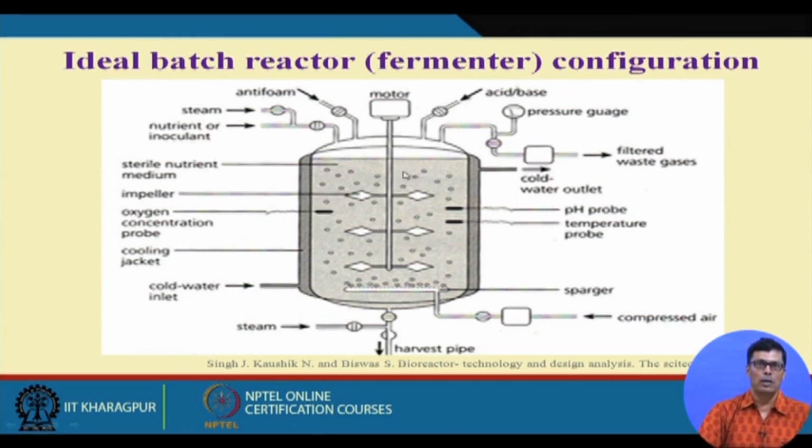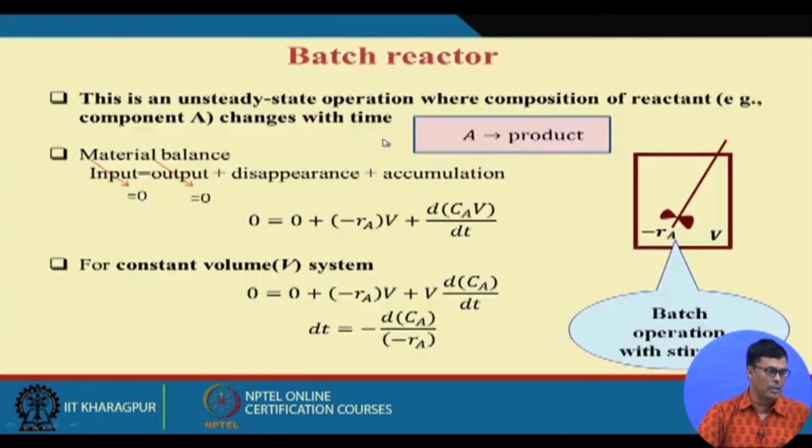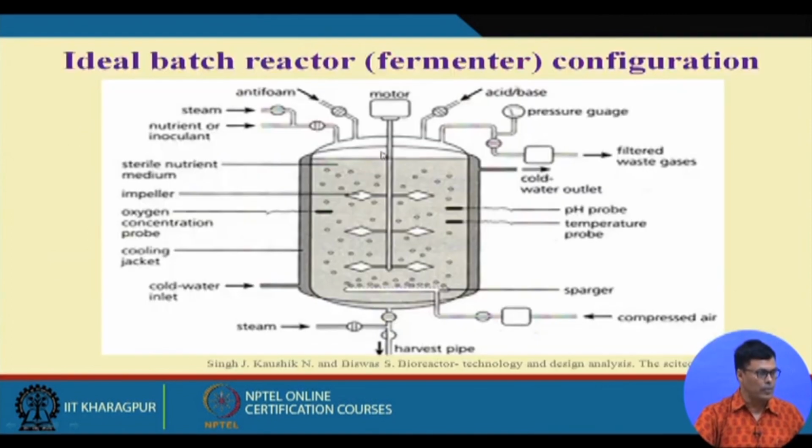So it should be perfectly airtight. To make it perfectly airtight, the air seal is designed, and if you allow the foam to grow, it will enter into the mechanical seal, the seal will be ruptured, and contamination will take place.